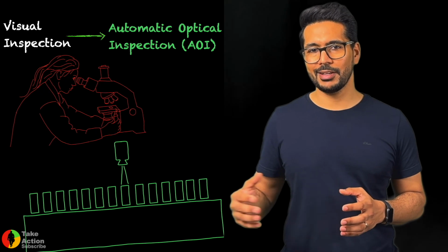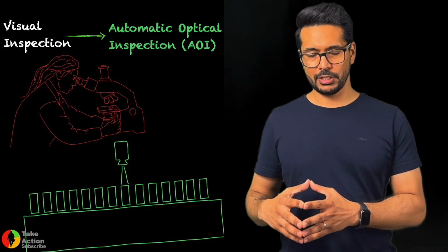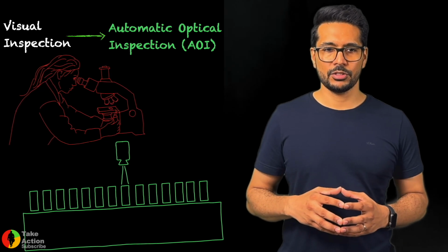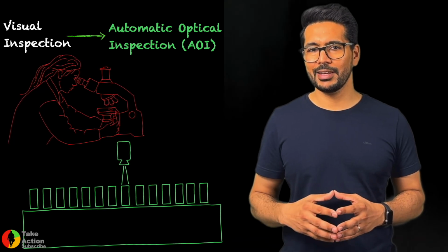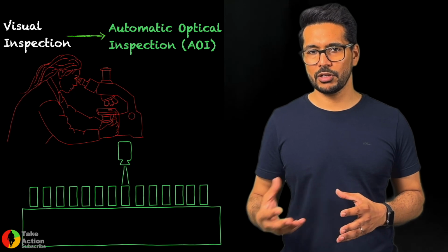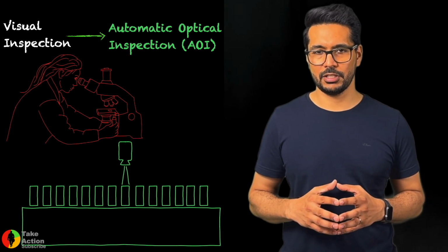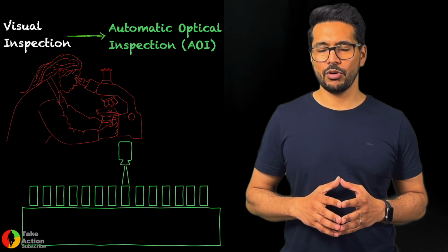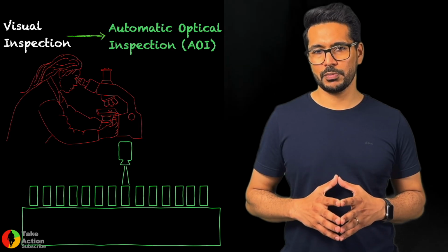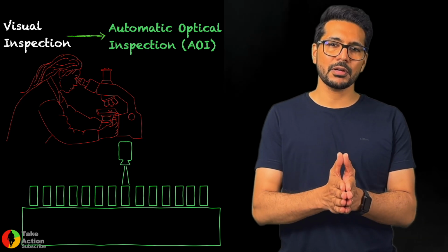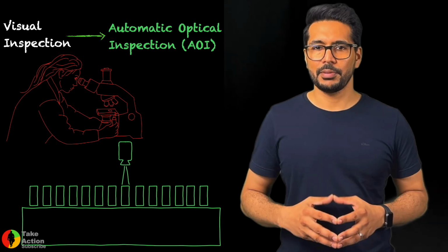So this can be optimized by automatic optical inspection, AOI. If we have a manual inspection process down the line, then it makes sense to have AOI, so that down the line we don't have to do any additional inspection. We save the cost, because normally AOIs are expensive. But in case we don't have any manual inspection down the processes, in that case, only to make the setup time quicker, we cannot buy an AOI.